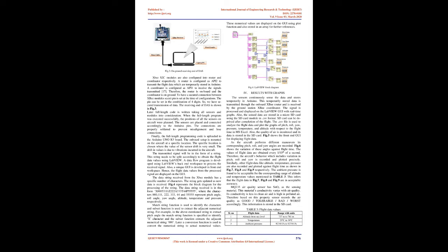4. Magnetometer sensor: the HMC5883L triple axis magnetometer is used for obtaining the yaw angle of aircraft. It is also used as a compass in aircraft. It has a standard I2C interface with a magnetic field range of ±8 Gauss.